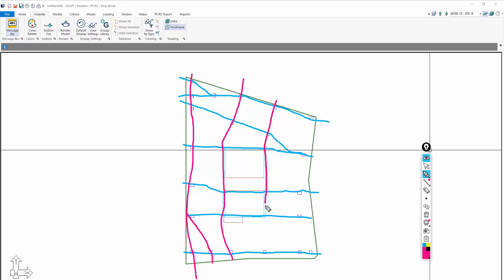And these support lines have to snap on column centers. They have to snap on beam endpoints if there are beams, wall endpoints. That's important when you're setting up the model to send it to Adapt PTRC, because that program has to interpret those components, and that presents the capability of the program doing that when we snap on certain component endpoints. So conceptually, we've kind of showed what we're doing here.